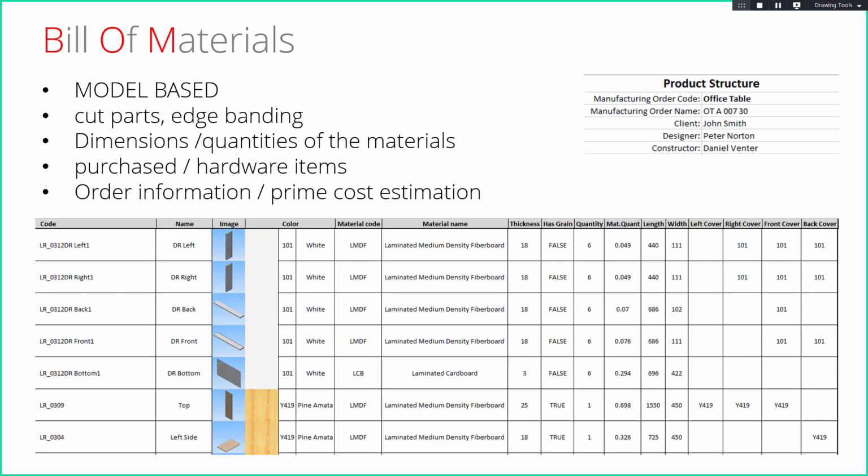And that's one of the examples of how the BOM can look. Why did I say one of the examples? Because you can easily control how the bill of materials looks by changing something we call a template. It's a specially formed Excel file which controls the parameters, and it shapes the bill of materials you're generating. Later we will see how it happens.